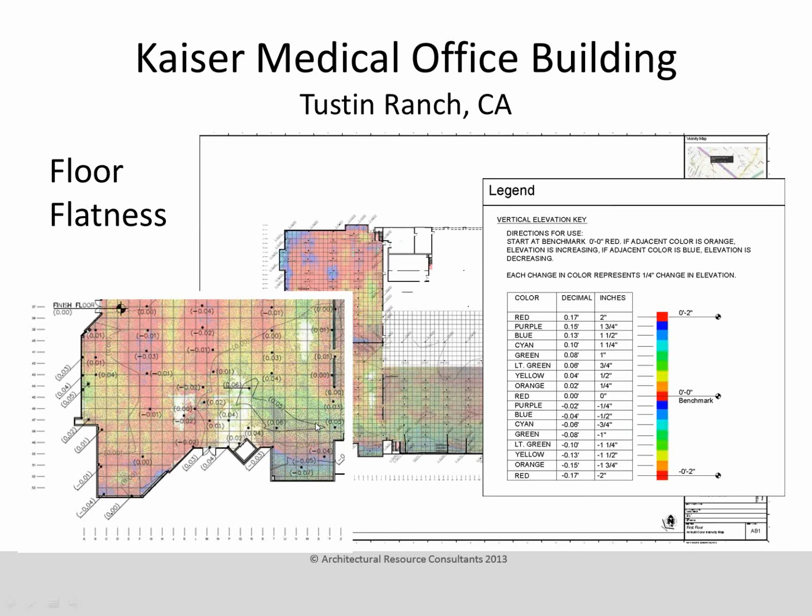We also shot this with a total station laser through a traditional survey process, and these are just random points kind of set up on a grid. And what was interesting about this particular project, we didn't know that the floor was doing this when we captured the data. So the total station shots were where these black dots are, and they just happened to land about in these red areas.